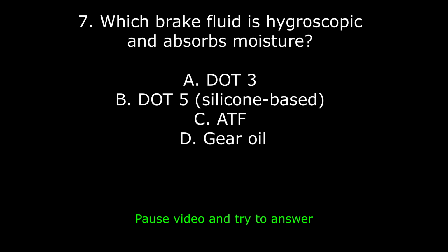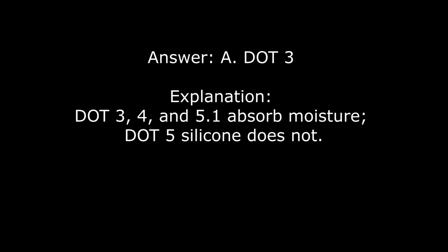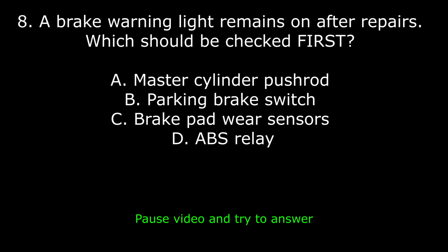7. Which brake fluid is hygroscopic and absorbs moisture? A. DOT3. B. DOT5, silicone-based. C. ATF. D. Gear oil. Answer: A. DOT3. Explanation: DOT3, 4, and 5.1 absorb moisture. DOT5, silicone, does not.